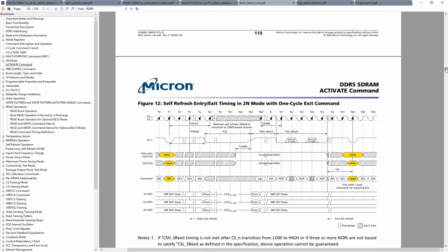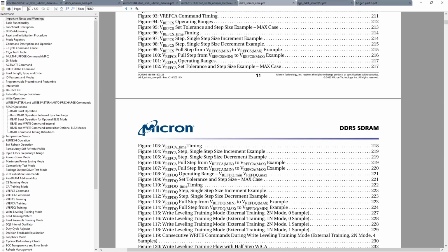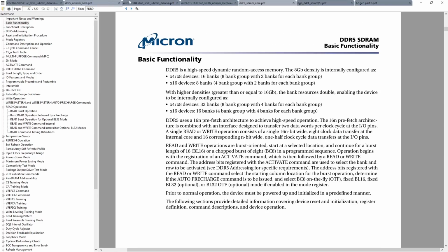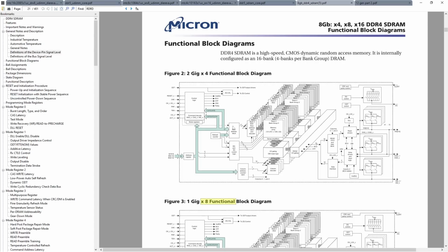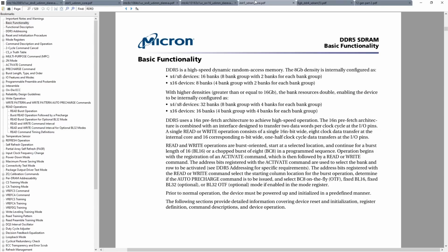And this is also why on DDR4 there's quite a performance uplift by having a dual rank memory configuration, because each rank of memory, assuming that you're using x8 memory chips or x4 memory chips, is going to have 4 bank groups in it. And so if you go from single rank to dual rank, in total you end up with 8 bank groups. And on DDR4, that means you get much more memory performance. With DDR5, however, because we already start with 8 bank groups, you don't really see much of a performance benefit by going from single rank to dual rank.